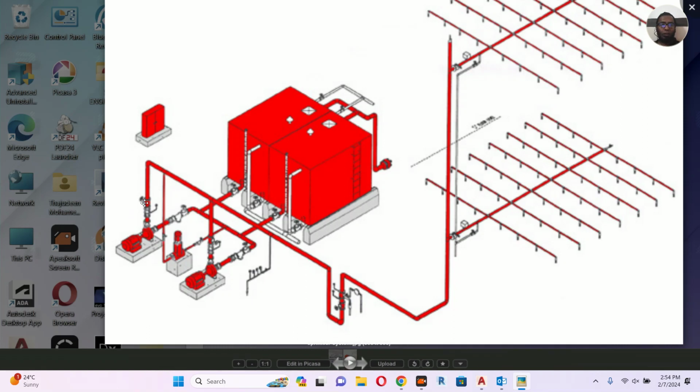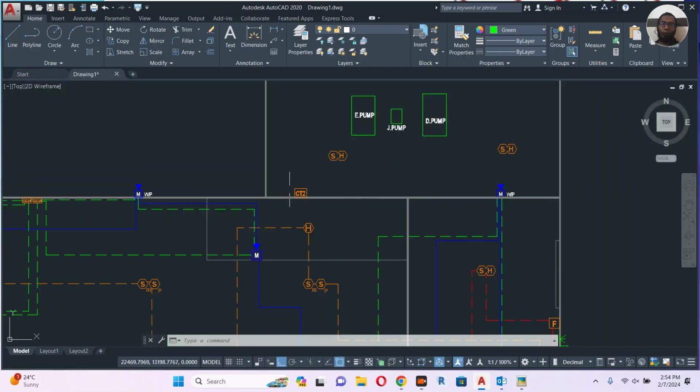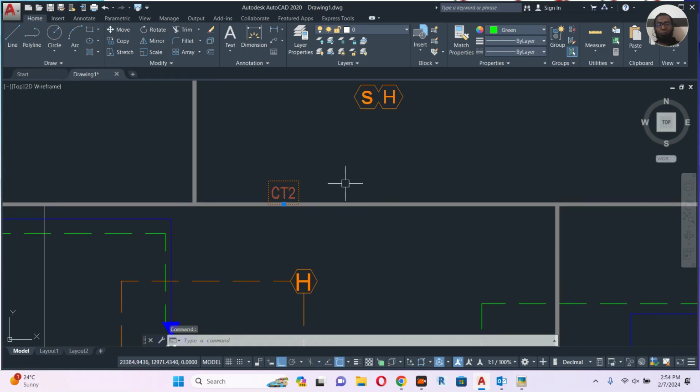Okay, so here we have to close this valve, this valve. Why two valves? Because if you want to replace the pump, you have to close here and you have to close here, then remove the pump and connect again and open. So here we have 3. It goes like that. So around 15 to 20, it depends. So minimum it's coming 15, so 10 to 15.